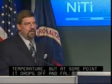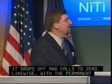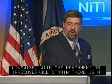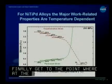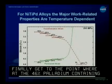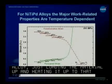Likewise, with the permanent or irrecoverable strain, there's a slight increase with increasing palladium content. And again, you finally get to the point where at the 46% palladium containing alloy, just loading the material up and heating it up to that transformation temperature causes the material to fail. So if you want to go to the next slide, please.